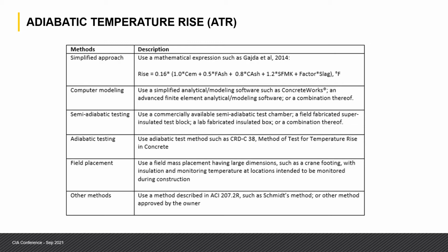Semi-adiabatic testing is one that I'm going to show in the next slide, but it's very commonly used in the North American market because it's a simple, heavily insulated block. You put the concrete in, measure the temperature of the concrete inside and outside, and then you're able to make the calculations and use computer modeling to determine the adiabatic temperature rise. Adiabatic testing by the test method is available, but it's rarely used. Its testing is rare because not many people have it available, and it also has limitations with time and cost.